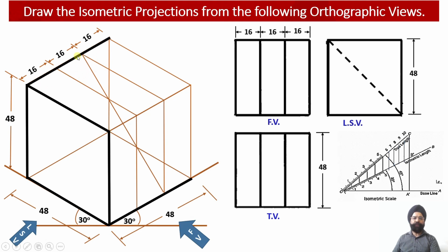Now looking at this object from the top, in the top view I am able to see all the 4 edges over here as dark ones, right? So this part I am able to see over here, whereas this portion is visible to us as a straight line in the top view. Even though this portion is empty because this is an inclined web and the upper portion of the inclined web has been removed, when we look at the solid from the top, this edge and this edge will appear to us as a straight line in the top view.